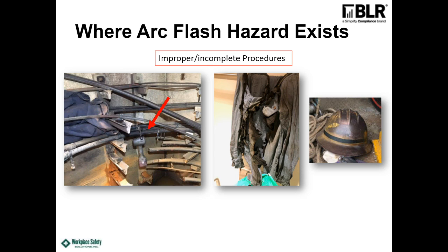This is using a tool that was actually cutting into a live wire, and this live wire has a shield on it that's grounded. So as you go through the shield and the phase, it short circuits to ground, and then there's a significant arc flash. You can see the clothing that was arc-rated clothing and the yellow hard hat that was being worn by that individual.